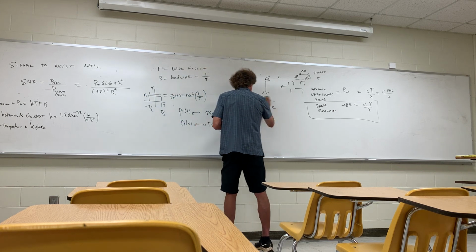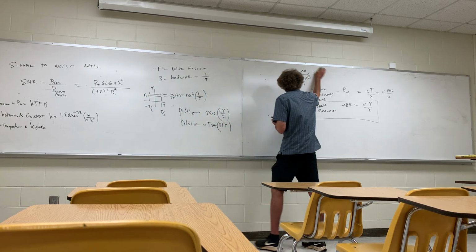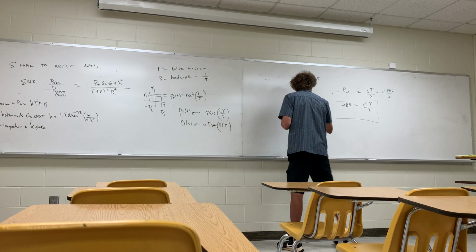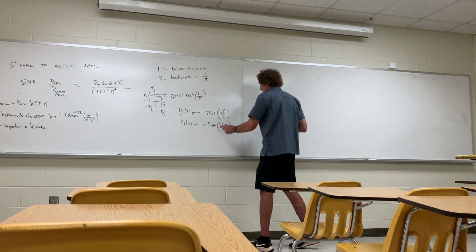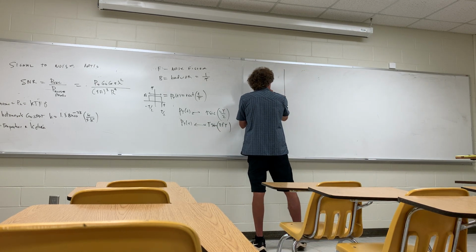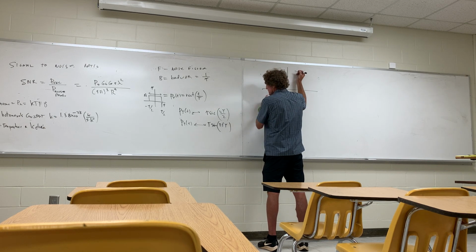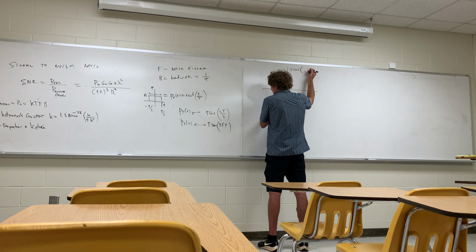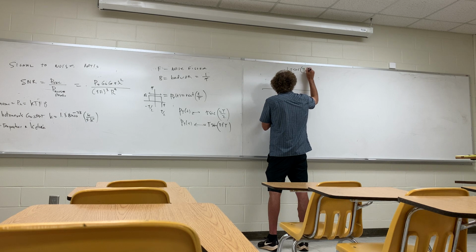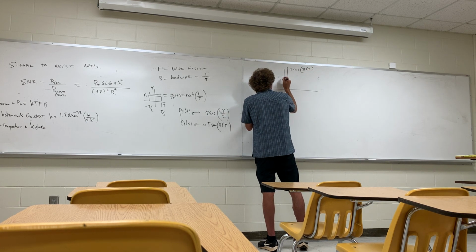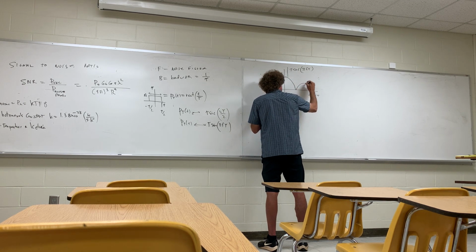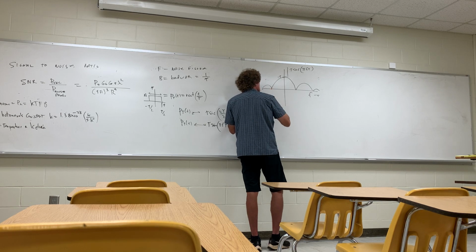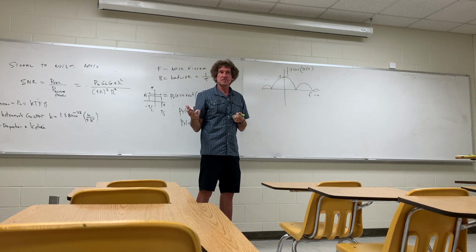Now, in the frequency domain, just so you understand how come bandwidth is 1 over tau, I'm going to plot the magnitude of tau times the sinc of pi f tau. It would have a peak here of tau, in the frequency domain, and then it would do this. That would be the envelope of a sinc function, magnitude-wise.